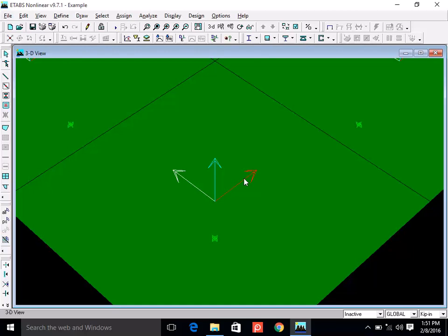End result is that maybe you provide more reinforcement in that direction and less reinforcement in this direction. So it will be opposite, right? So if it is opposite, then definitely your slab is not going to survive, or it will have cracking. So be very careful in reading these moments, because these moments are ultimately translated into reinforcement. Okay, so make sure you understand this local axis system.